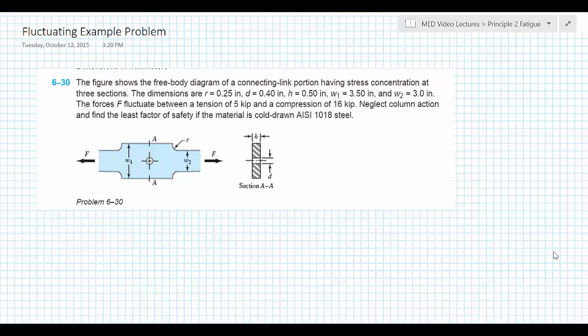So recall, anytime we're talking about crack failures, cracks are real things that happen in real places. So we must be really clear and specify where it is that we're concerned about a crack growing. In this particular instance, we have an odd-shaped bracket type thing, which has both a fillet and a hole. Every time we see geometry change and we know that there's stress, there are going to be stress concentration factors, but it's not super clear right now where that stress is going to be highest.